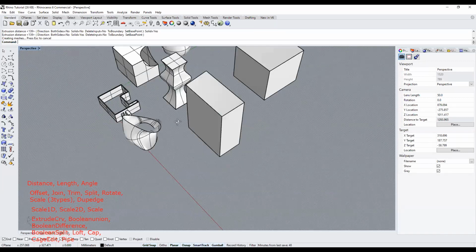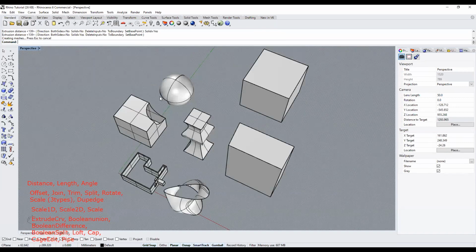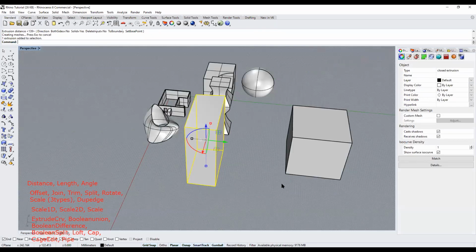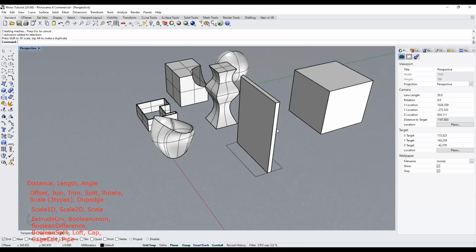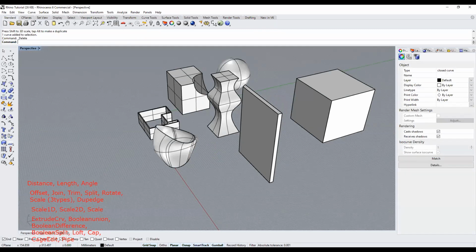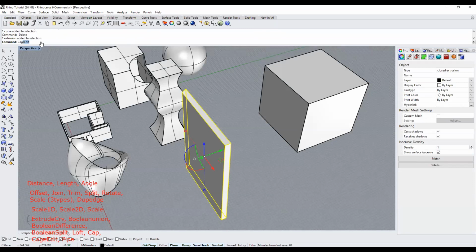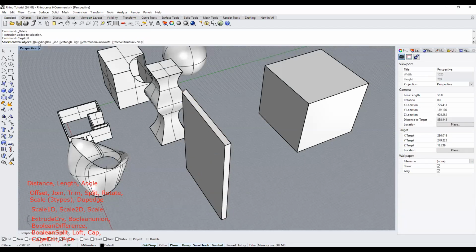So yeah, for cage edit, this is where it gets kind of inaccurate. You're just manually creating a really organic shape. When you type in cage edit, you select bounding box, C plane, and you get to control the cage parameters, like how many points I want going this way. I'll just demonstrate what it does first.